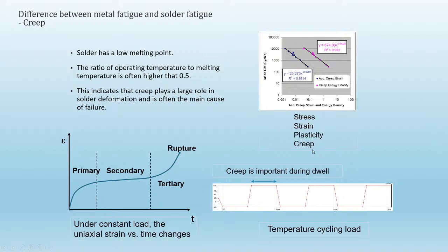So this is why you see most of the folks that are developing packages that look at solder reliability typically use a more advanced model, whereas teams that are integrating existing components and not adjusting for the solder shape or the package foot design will use a more simplified manner because it'll be faster to solve. So there are a lot of different ways you can do fatigue analysis for solders, but the one we're focusing on today is using a creep model to get the most accurate method possible for solder joint reliability.